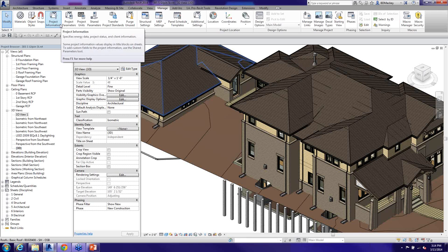Well, in the default out-of-the-box template, your location is Boston, Massachusetts, because that's close to where the Autodesk programming facility is for Revit. So that's going to be your default location. So if you're down in sunny Florida or something, you might be wondering, man, why am I getting the shadows more intense in the winter than I would expect?